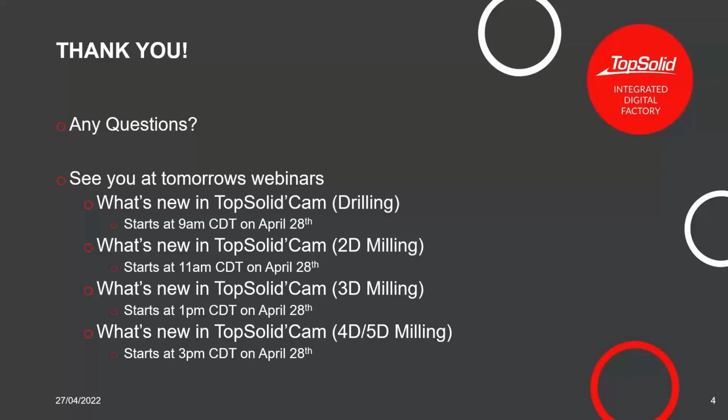Does the method automatically choose interpolation versus dedicated spot face tool based on the availability? So I suppose you could set up a rule that way. For me, I set up my rules for the spot facing based on sizes, because the standard spot face tools only go up to a certain diameter, and then you switch to an end mill and interpolate it anyway. Some people interpolate everything. So, you could go into the method I have, copy it into your own library, and just delete the section that grabs the spot face mills. So at the end of the day, you should be able to get to your finish line.